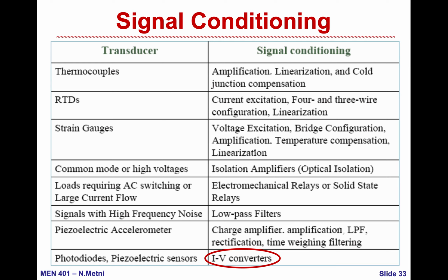Okay, by going back into the first slide of the first part of this signal conditioning lecture, now we can see that most of these signal conditioning were covered. We still have one, which is the IV converter. I will not stress on it a lot, but I have to cover this here in order to be complete on the signal conditioning side, and in addition, this standard of IV, or what we will call the 4-20 standard, is largely used in most sensors in industry.